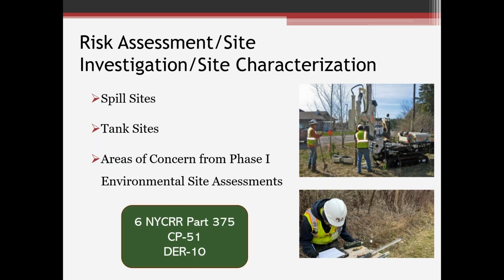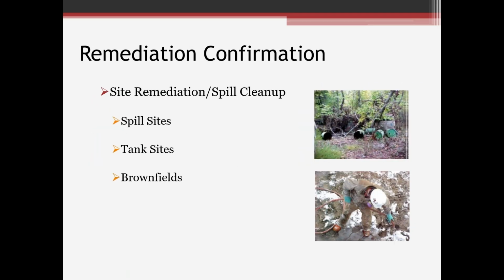So with that, you're looking at Part 375, the soil cleanup objectives, CP51, DER10. Some of those would be used in concert with this type of soil sampling application. Remediation confirmation, so site remediation, spill cleanup, whenever you're doing that type of activity, you're likely going to want some soil sampling, to see how things are going.